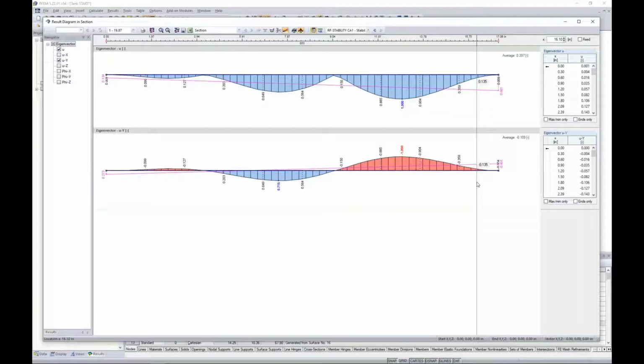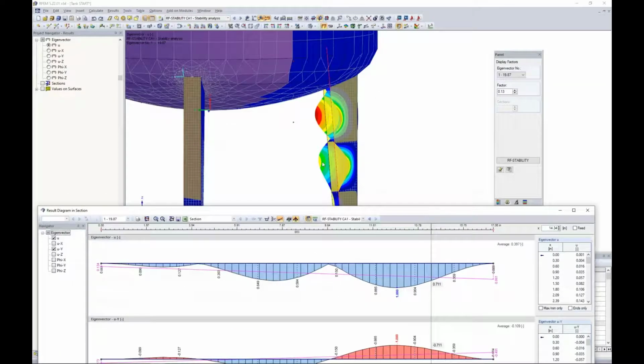The reason that I'm doing this whole procedure is because I want to relate this buckling to modeling imperfections. And we all know that when we are constructing a tank or any type of structure, there are installation errors, maybe incorrect construction methods, or we don't properly manufacture the elements, and inevitably we have imperfections. Everything that we are modeling within the RFEM program here is essentially perfect, and this is true for any general finite element analysis. All lines are perfectly straight. All elements join together at every FE mesh point, when we know that in reality, lines probably won't be straight. Surfaces aren't all in one plane. Mistakes happen, and there are tolerances that are given for these mistakes.